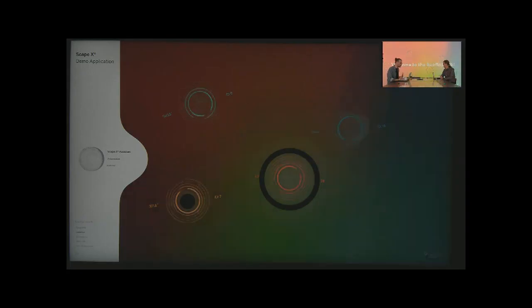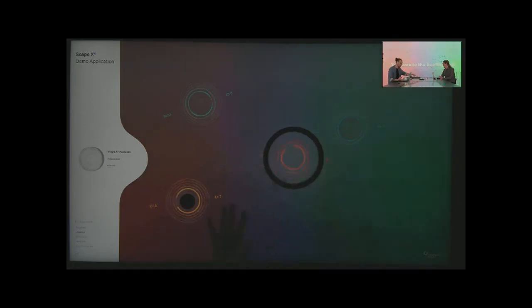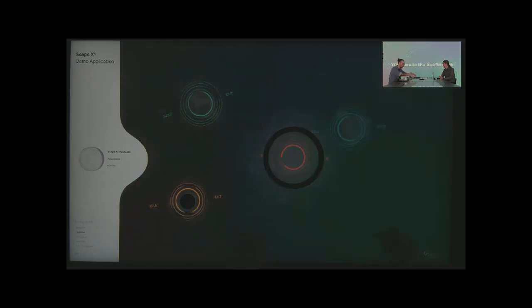So what is now special about Scape X compared to other object recognition systems? Scape X connects AI or neural networks with high-quality PCAP data. While conventional PCAP displays only detect touch points and translate some combinations of them into objects, our Scape X engine goes deeper, recognizing and interpreting the underlying individual capacitive effects of things. Thus, a touch point from a finger is something completely different than a tangible object from the point of view of our engine, so to say.